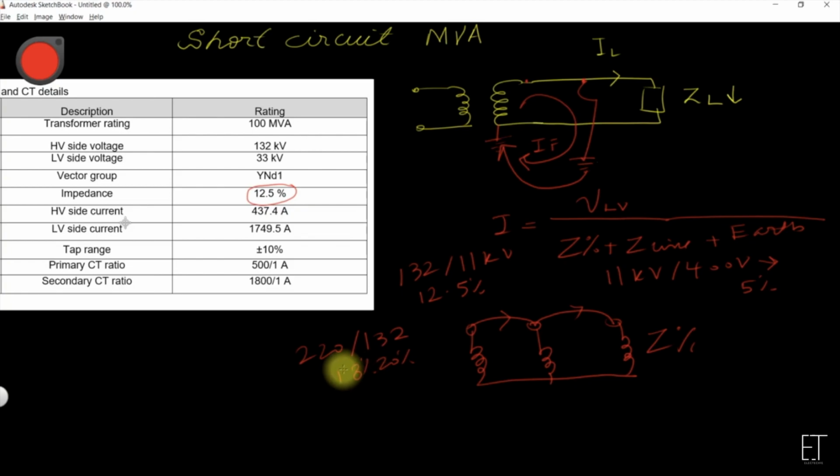So if the voltages are increasing, the fault levels are also increasing, and we want to control the fault current in that case. We can control the fault current by increasing the impedance of the coil itself, because this is the limiting factor in case of a fault on the terminal of the transformer. And we design the transformers for the worst possible fault condition, and that is normally a three-phase short circuit.